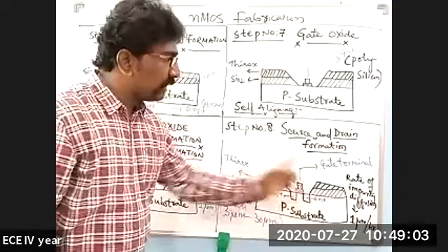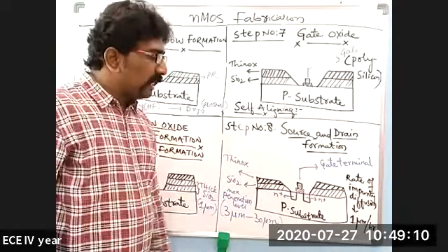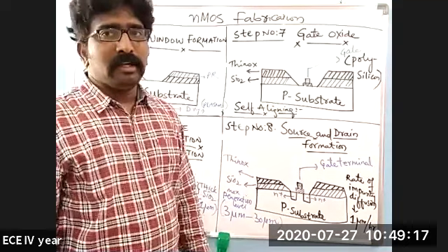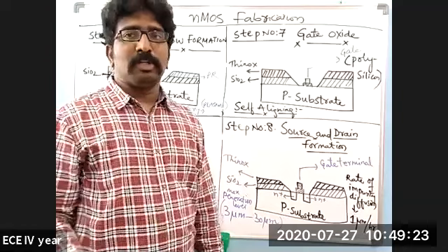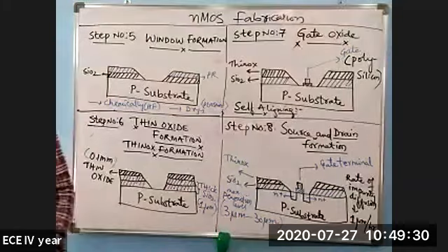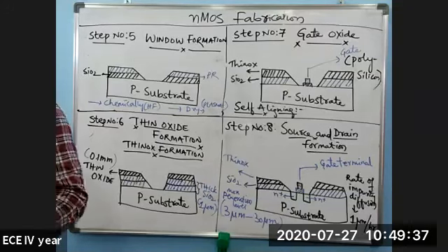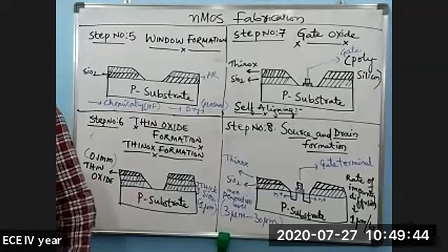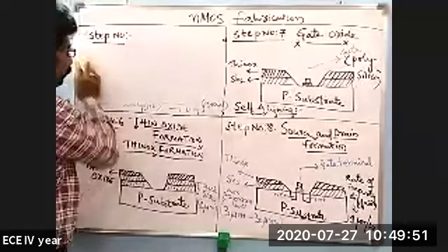source, and this is how a source and drain will be formed, by diffusing n type impurities after subjecting the substrate to 900 degrees Celsius to 1200 degrees Celsius. The material used here for n type impurities will be phosphorus, or PH3, phosphine gas, which is used for diffusing n type impurities. So please note it down. I'm erasing these first two, fifth and sixth steps.